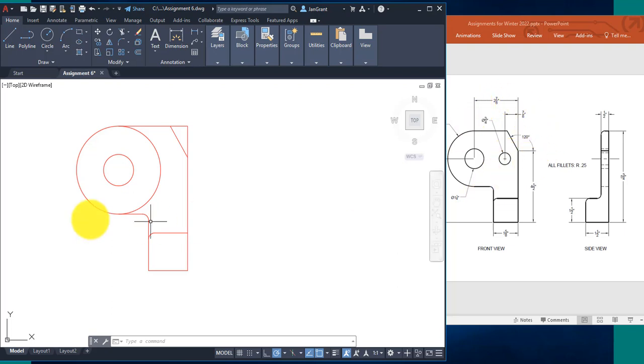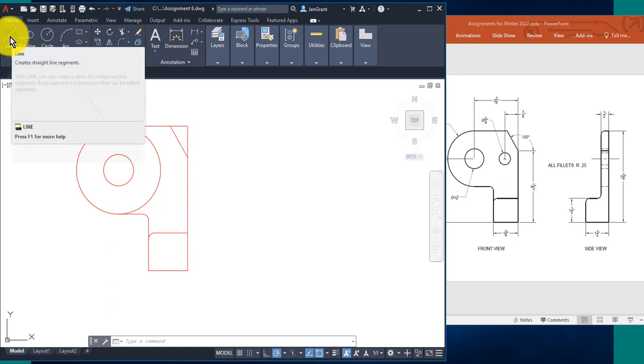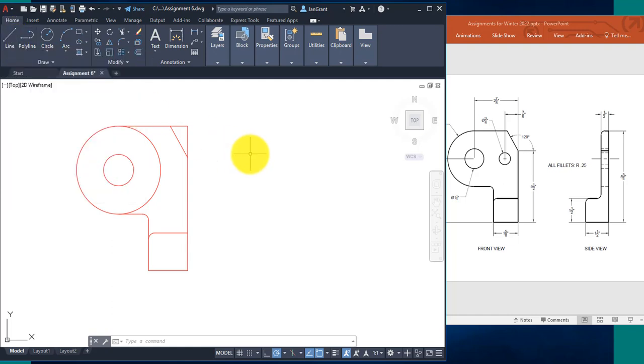And since we have 2 inches from this side to the bigger circle and 7/8 from here to here, we're going to do a little math and find out that it's 2 inches from the center of this circle to the center of the smaller circle. Now you could track there like I just have been doing, or you can just draw a line from the center of this circle over to and then draw your smaller circle. But I really like the tracking idea, and I'd like to show you this.